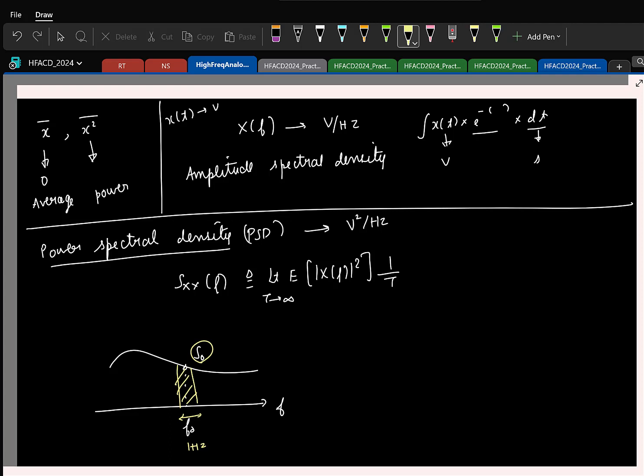This is the same as your probability density function, right? If the probability density function is not 0, it doesn't mean that at that instant the probability is that value. So only if you have impulses in your density function, let us say an impulse at a frequency f1 with an area s1, then you can say that my signal has a sinusoid of frequency f1 and the power of that sinusoid is s1.